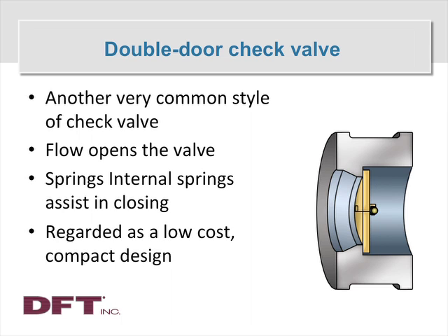They're difficult to get tight shutoff with because of that plate that's splitting in the middle. You've got a very difficult shape to try and seal fluid against. But the face-to-face standard for these valves is typically an API 594 face-to-face standard. Again, low cost and might be a valve to consider in applications where you've got tight spaces and maybe dealing with high alloys, where a big heavy valve is big and expensive. They're not an uncommon valve at all. You'll find them in a lot of applications.